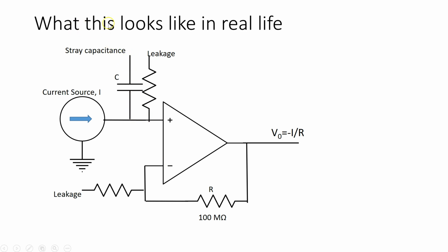So if you've got any source of an oscillating field around here, and the capacitance is even a picofarad or so, and a picofarad's a very tiny capacitor, so you can have two wires that are parallel to one another and even a centimeter apart or so, and they can generate picofarad capacitances. So there are picofarad capacitances all over this thing, connecting this op-amp to other places.